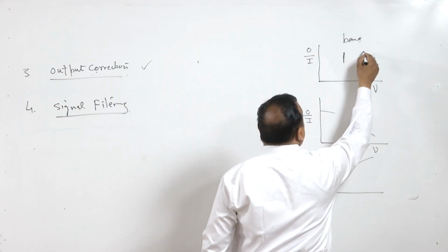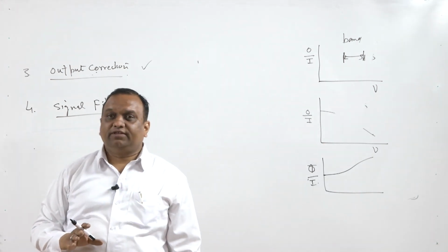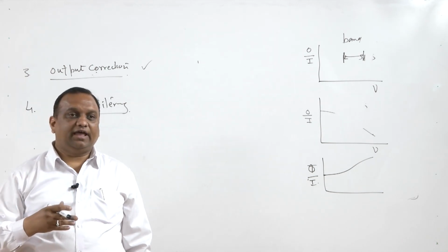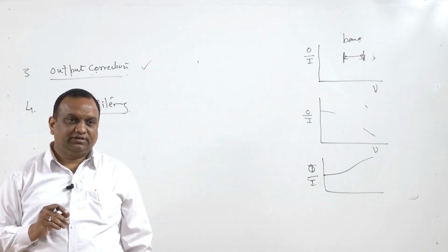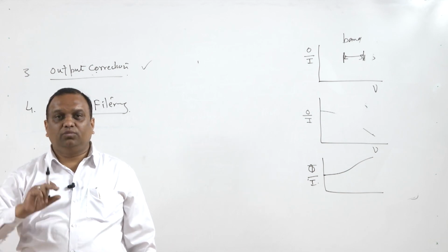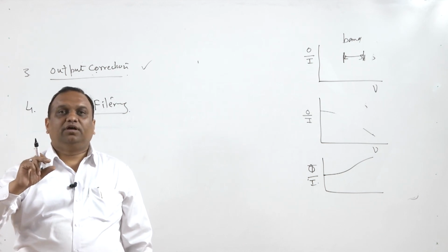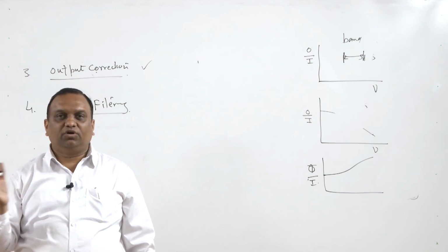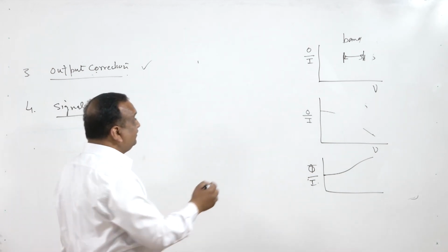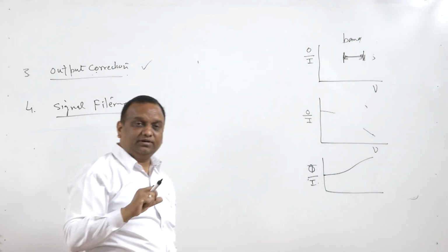Which allow only a certain range of frequency to pass. Suppose there is an interfering and modifying input at 50 hertz and 100 hertz, right? So you can say that you will allow frequency between 75 to 100 hertz, so that you can avoid the interference from 50 hertz and 100 hertz. So they are known as band filters, which allow a certain band to pass through the filter.